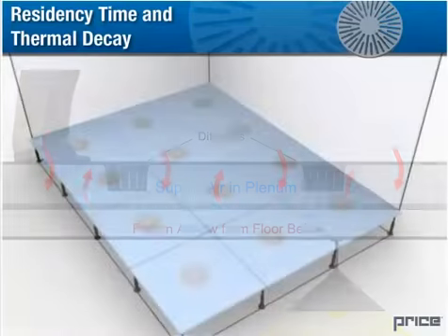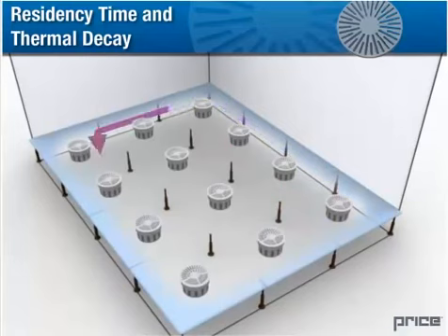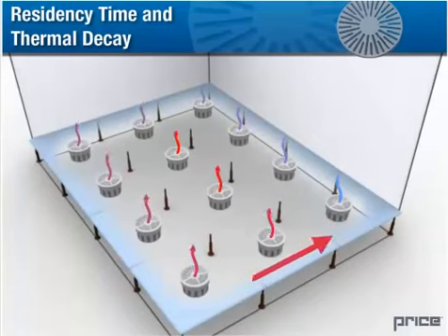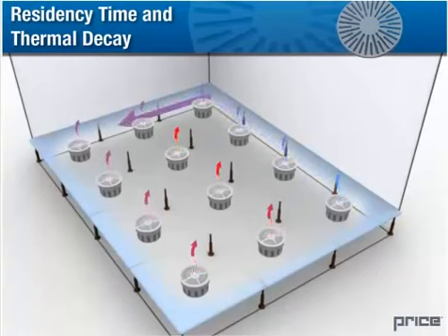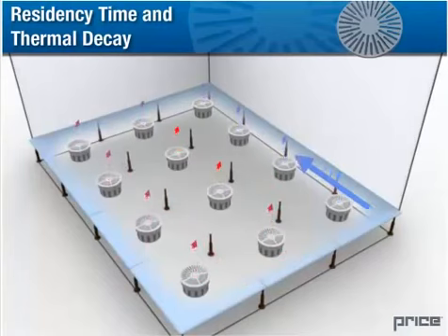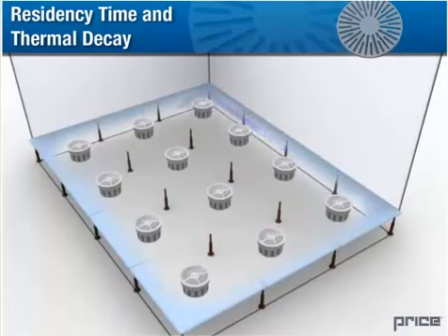from the floor below. The longer the supply air is in the plenum before entering the zone, the higher the exit temperature will be. What's more, wide temperature variations throughout the plenum and diffusers can occur, ultimately leading to discomfort in the occupied zone. This problem could be reduced with careful plenum design. The residency time and thermal decay is related to the airflow patterns in the plenum. The farther the air has to travel in the plenum, the longer it takes to be fed to the space.